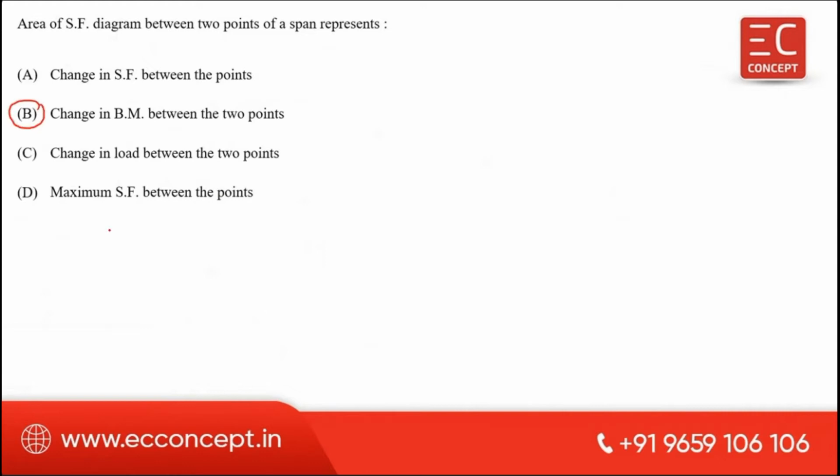We know the static equations: one is dV by dx equal to intensity of load, another one is dM by dx equal to shear force. Now take this second equation, dM by dx equal to F. So dM is equal to F into dx.